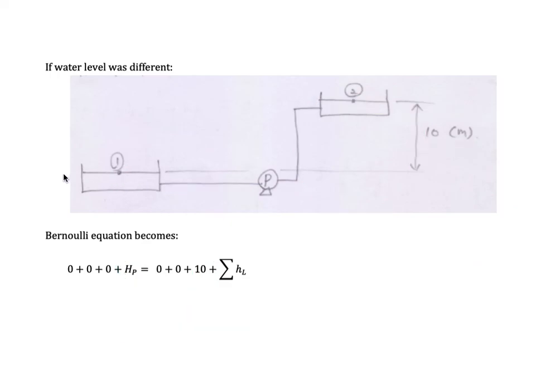Okay, these two calculations are actually to predict the pipe system connecting two tanks, to make sure that it works in normal condition. If you have the theoretical value and you could calculate the flow rate and the velocity in the pipe, then when you check the real side, you could make your judgment. If the flow rate is not the same as your calculation with losses and so on, it means that there's something wrong in the real situation. So this is the idea of this calculation.